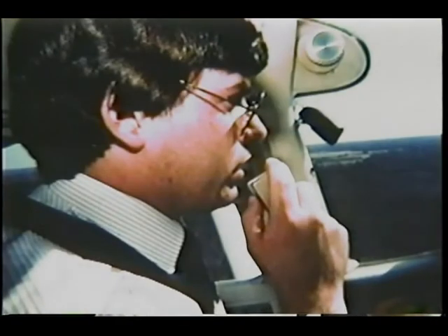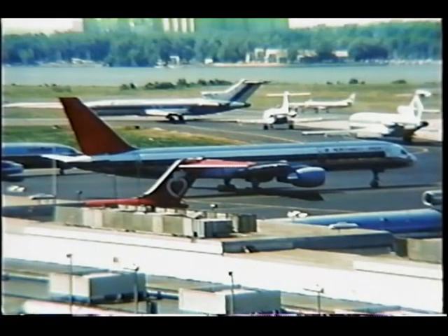Now communicate. Remember, control first, then communicate. There is no exception to this rule. However, if you're at an airport with a busy control tower, it's prudent to tell the tower what you're up to as soon as possible, but never at the risk of compromising your safety.